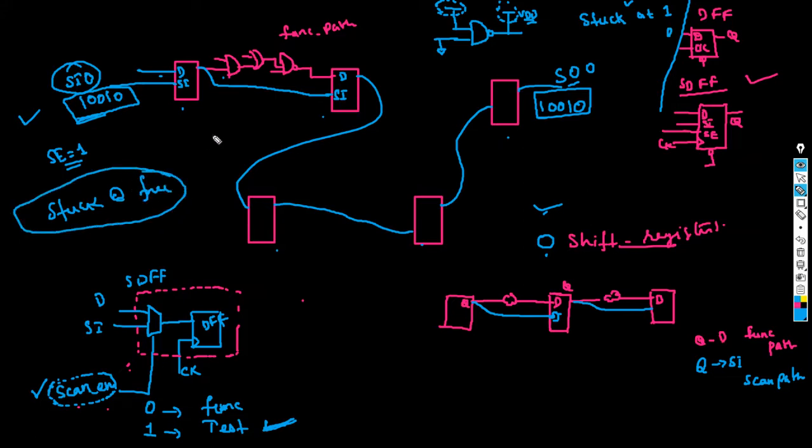Now imagine that this flip-flop Q is stuck at 0 always. What would your value be here? Throughout this node, if anything gets stuck at 0, you will see only 0, 0, 0. This way, with the help of shift registers, we are able to figure out if the chip is free from manufacturing faults. Remember, stuck-at is something people also call manufacturing faults.